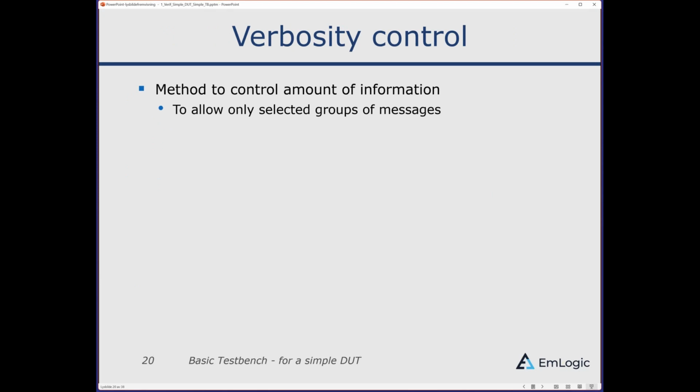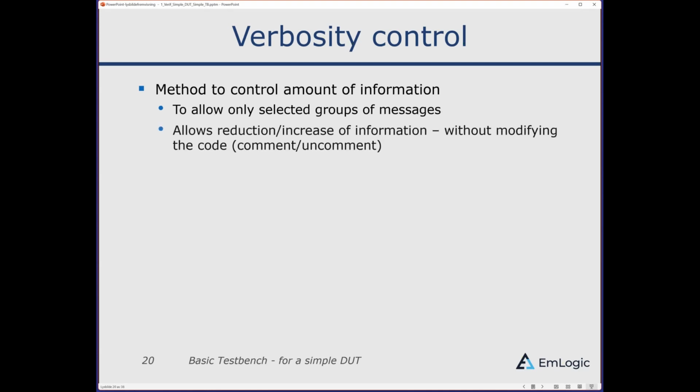Then you have alert handling, and alerts are intended for messages that may or may not need attention. They could be any severity from note to failure. And of course, you should use that severity to indicate the severity of the alert. And then on top of the logging and alert concepts, we have all the checking, await methods, and so on that you need in any test bench.